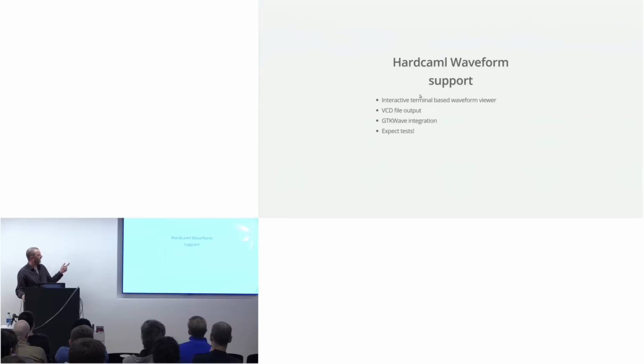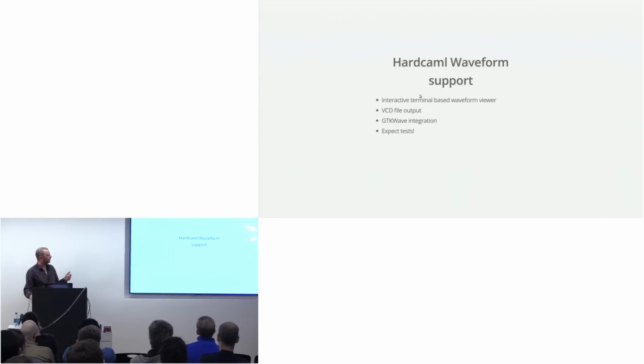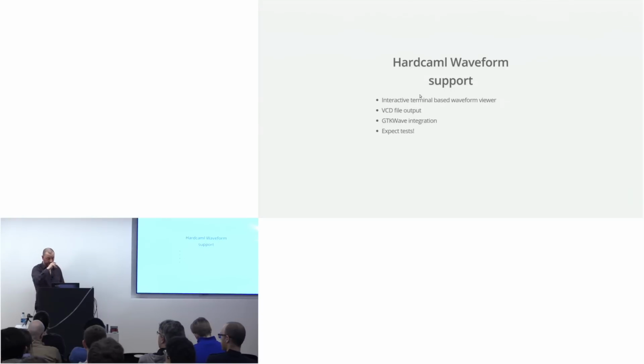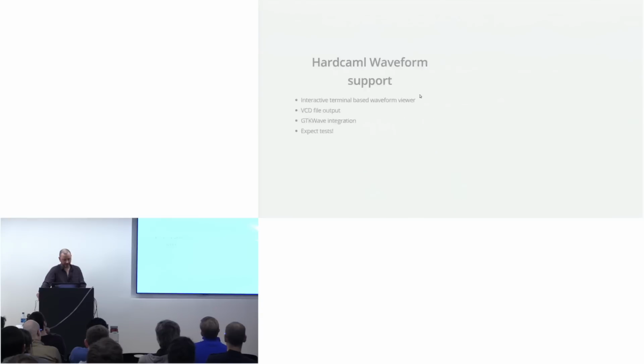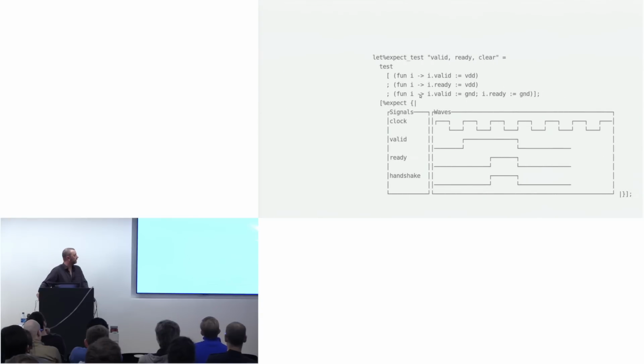There's also a bit tighter integration with HardCaml simulation in that it can start a simulation, fire up GTK-Wave, and pump data across to GTK-Wave for it to be viewed while the simulation is actually happening. And a new feature is we now have waveform expect tests, which are super cool. You may have heard we quite like expect tests around here, and they look like that.